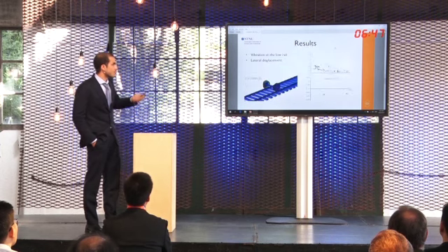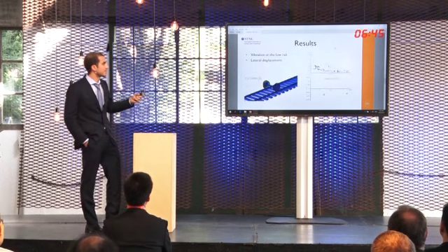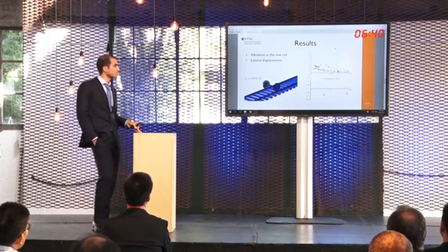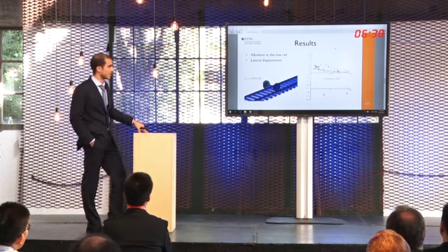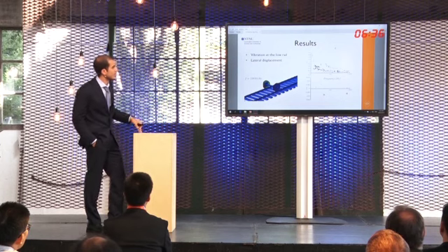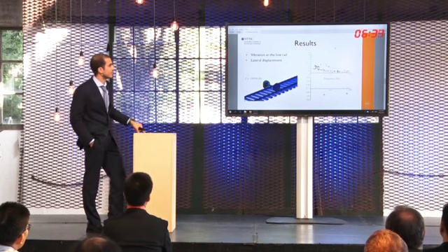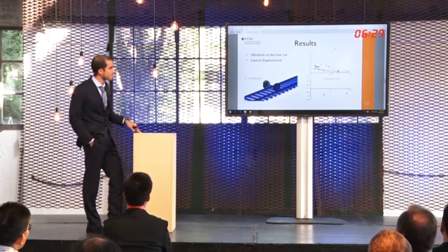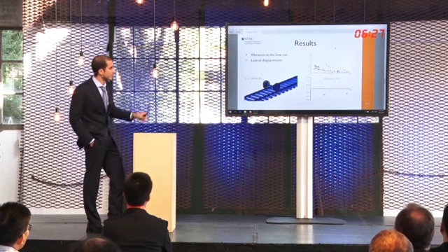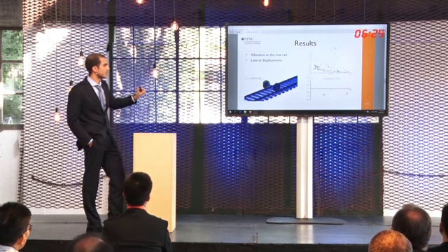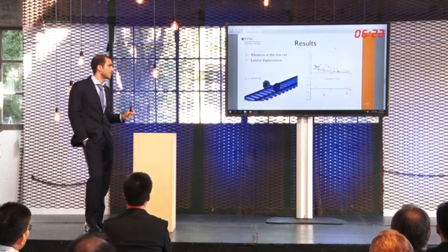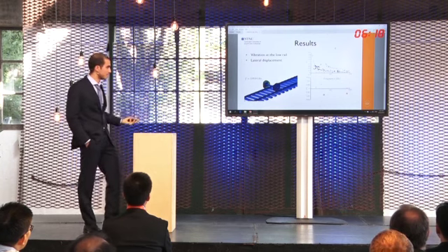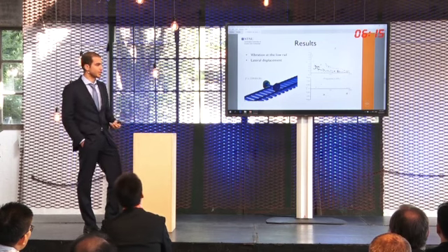All right, here we can see the results of the analysis in terms of just one of the cases of our parameter analysis, where we have got instability. On the right upper part of the slide, we can look at all the effective damping ratios detected in our frequency range, while on the bottom, we can look at just the near-zero effective damping ratios. As we can see, there are 2 negative effective damping ratios, therefore related to unstable vibrations.